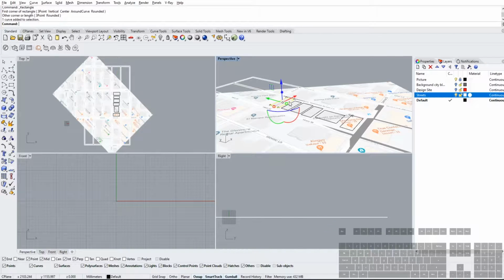Okay, now we're going to extrude these to have the approximate height of each one of the buildings. You can do this by going onto Google Earth, Google Maps, anything that's 3D. You can kind of tell how many stories they are, and by that you can multiply by a different height. Since mine is kind of a made-up scenario, I'm just going to do an arbitrary amount.